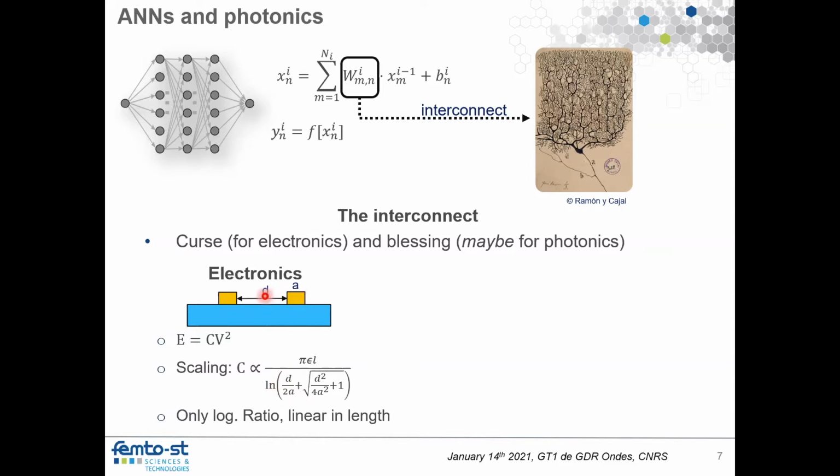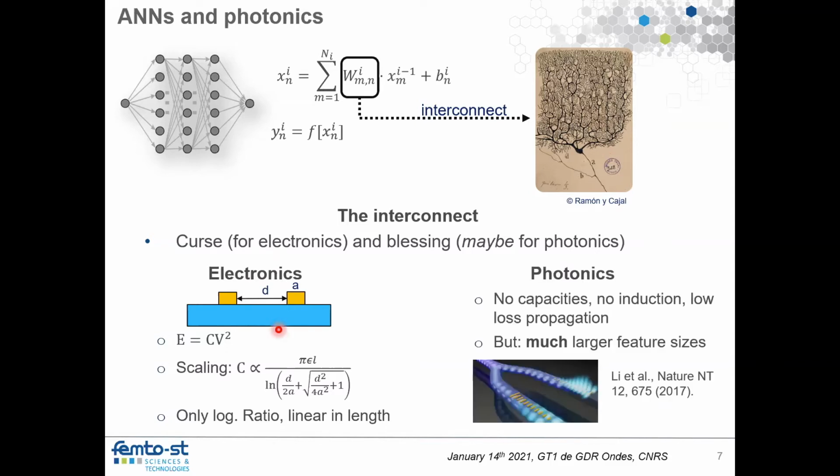So in other words, if you reduce the size of electronic integration, like it's always done right now in these different technology nodes, where you go down to 12 nanometer, which is commercially exploited right now, essentially all you can hope for is a linear scale improvement. And this is essentially what leads to the performance limitation in today's integrated electronics because of the dynamical switching energy associated with switching electronic wires.